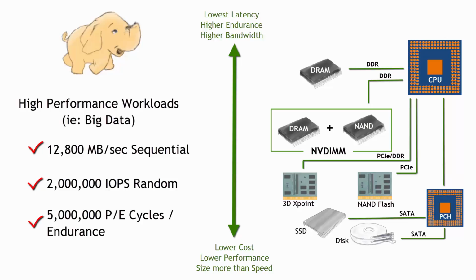This isn't convoluted with multiple systems. It's all built within this board here, this NVDIMM, and it will preserve anything in DRAM before all power gets lost to that server. Upon reboot, essentially the DRAM is checked for its state, and then it recovers itself from NAND if needed to bring it back up to speed.